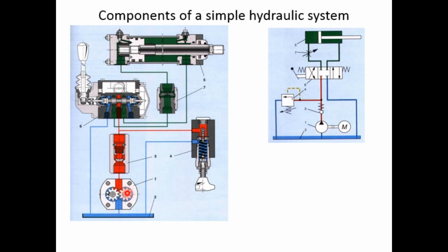Okay, here you have the pump, number 1. The pump is shown by just one circle and one small triangle, and the triangle is filled. Then you have component 2, which is the tank. So the tank is shown here directly. Then the third component is a check valve, which allows the flow of the fluid only in one direction. That is what is shown over here by this particular symbol. And then this pump is coupled to a motor. The pump is shown by a circle, and the motor is shown by marking M at the center of a circle.